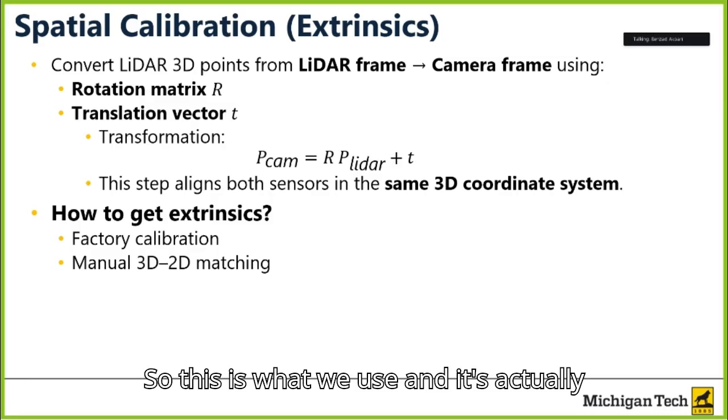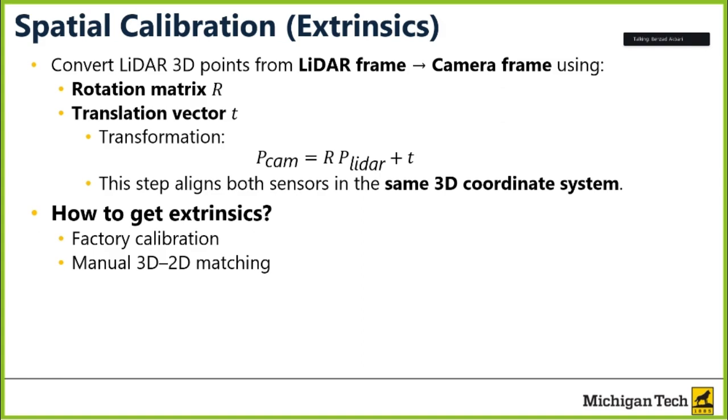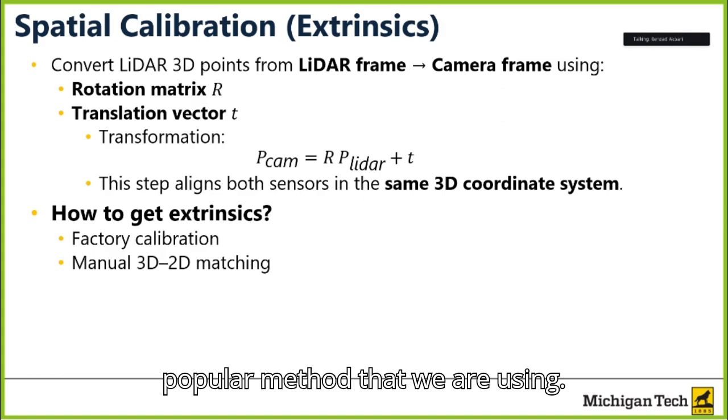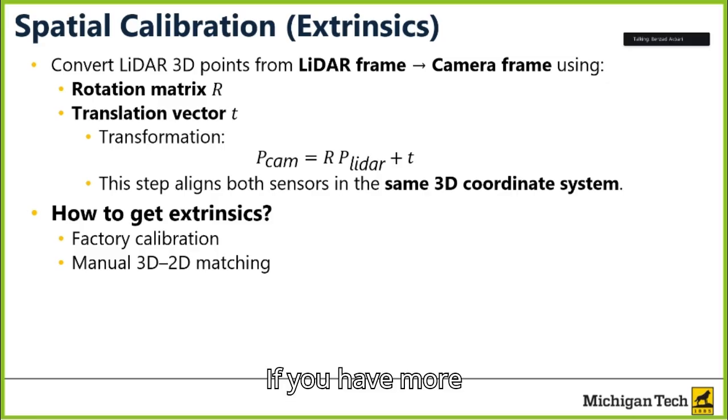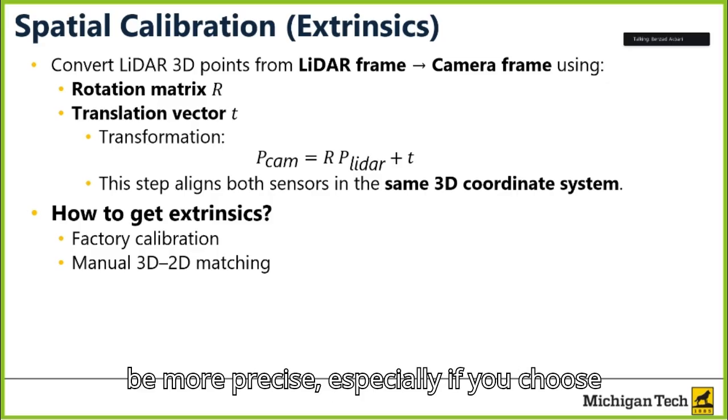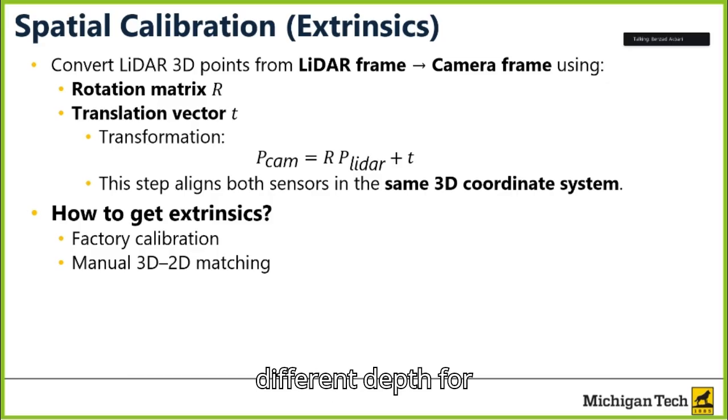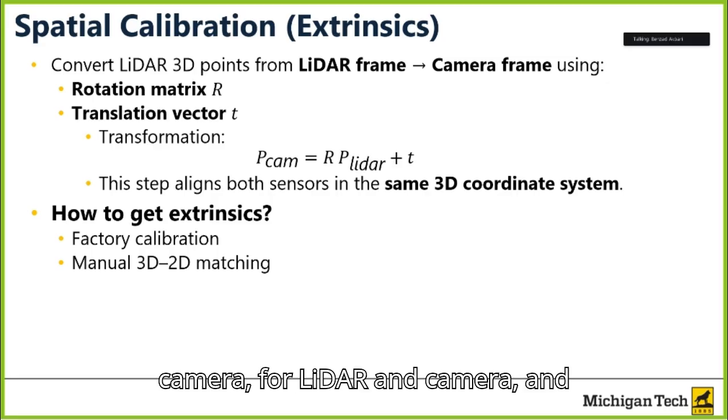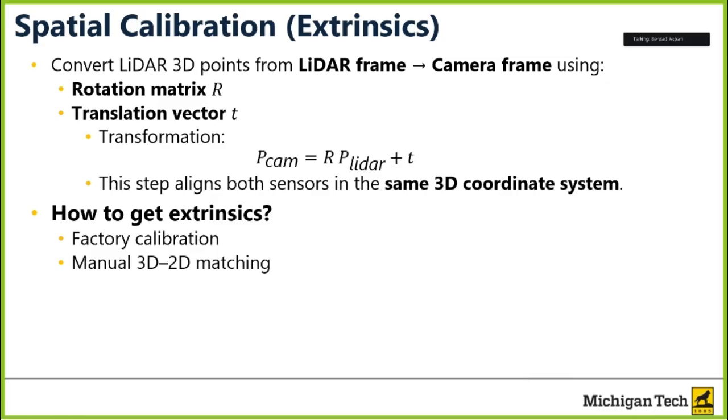This is what we use, and it's actually the more popular method. If you have more matching points, it should be more precise, especially if you choose different depths for LiDAR and camera, and that's going to be very helpful.